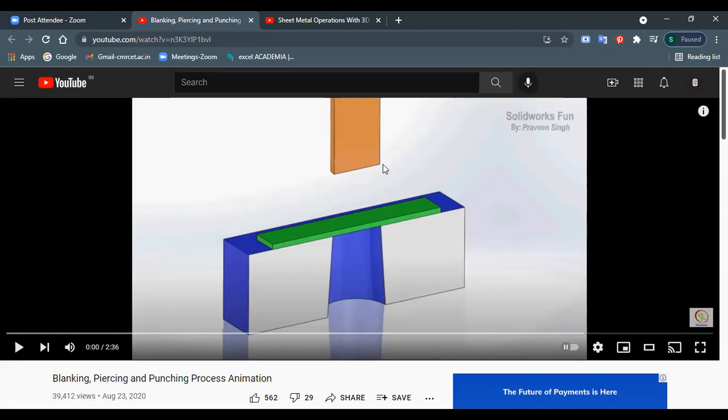So if it's a circular punch, then you have the diameter difference. If it's square or prismatic, then you have it in terms of breadth and depth. That is what is responsible for the shearing action. It presses, it tries to compress, but only until the material fails, and it fails by shear. So that's what is happening, the shearing action.